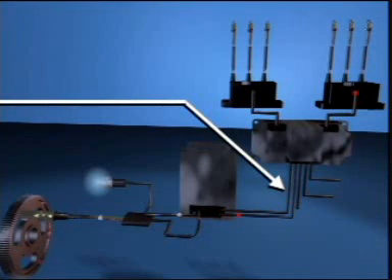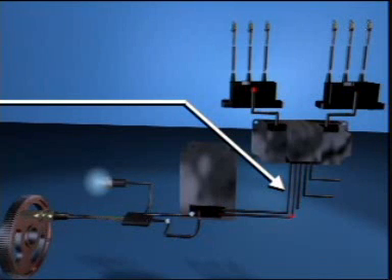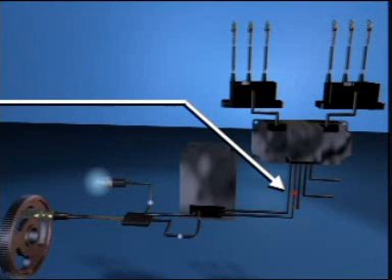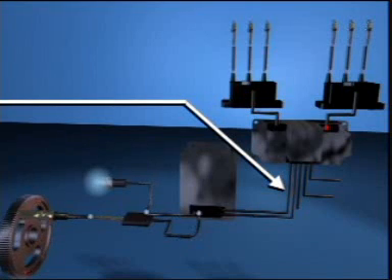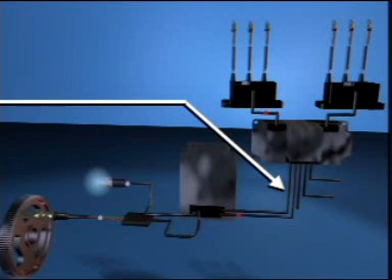The spark reference signal from the ECM to the ICM indicates to the ICM that cylinder number 1 is next in the firing order. The ECM receives the input from this signal from the engine position sensor and the 7th protrusion on the camshaft gear. There is 1 spark reference signal for each 6 spark timing signals.